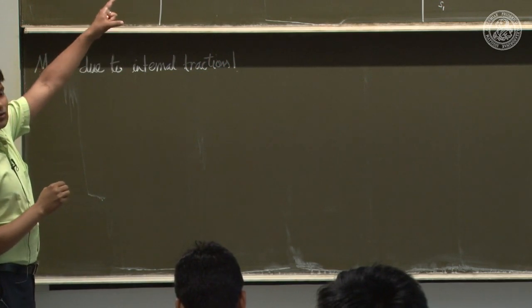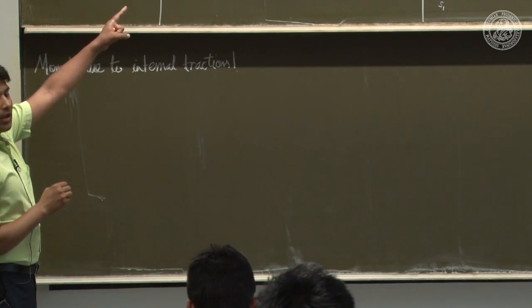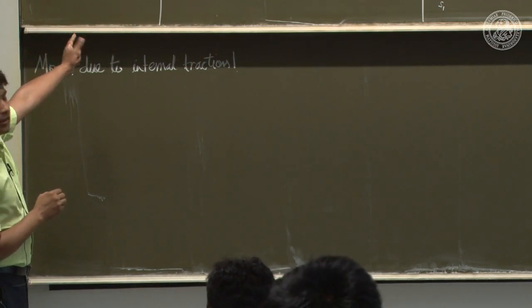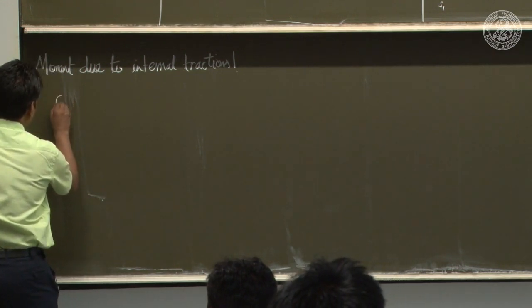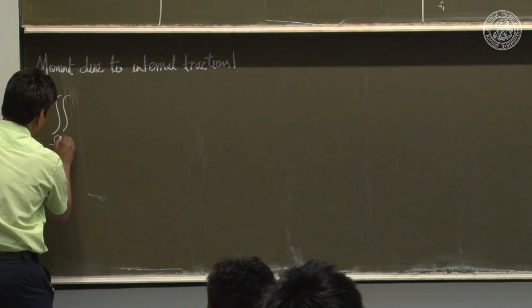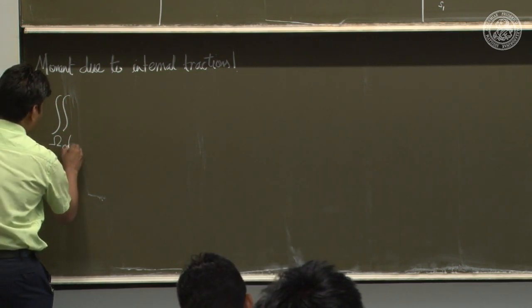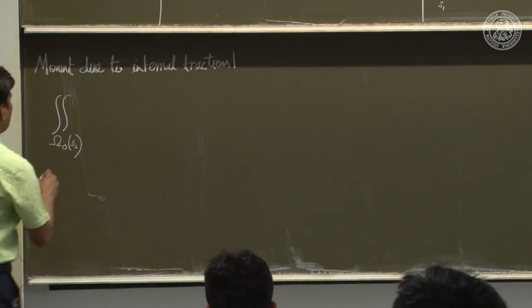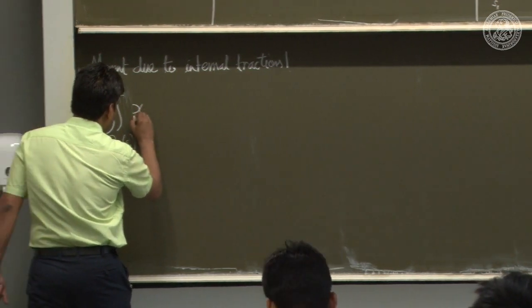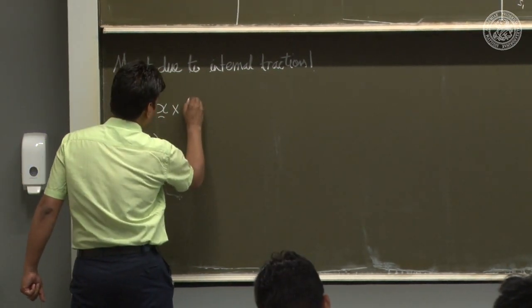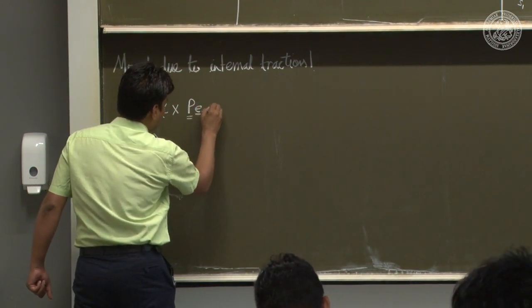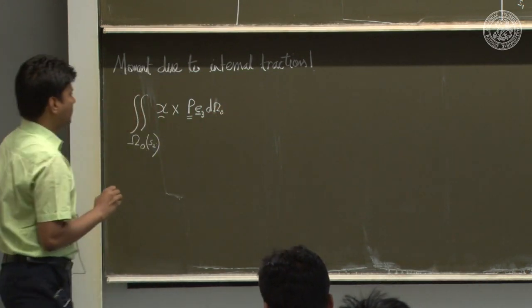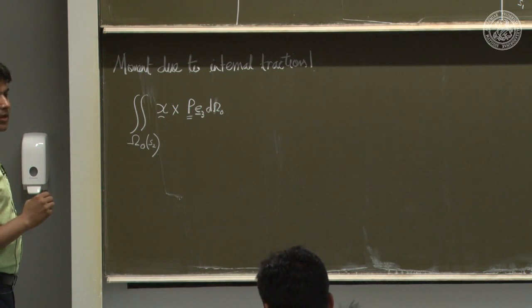So we first look at the S equal to S2 cross section and find out what is the moment due to those tractions about the origin. So that is again going to be equal to integral over that cross section omega naught, which is at S2, right, the cross section at S2, and you have little x cross P E3 d omega naught. Right?